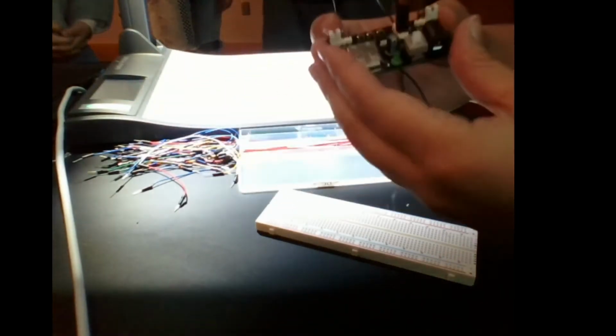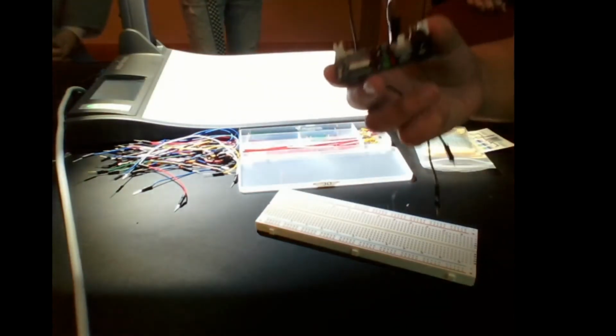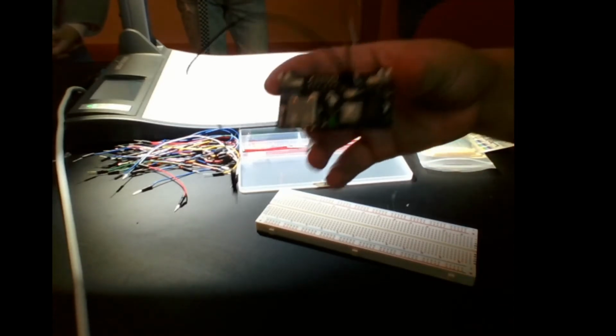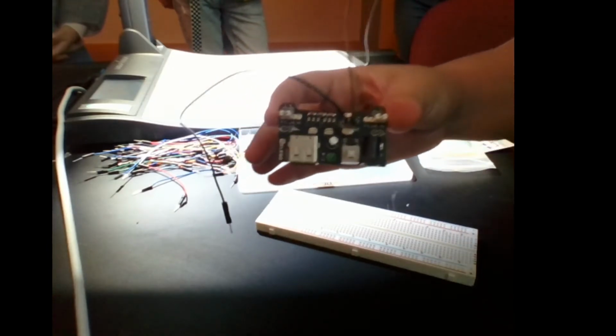Alright, so this is the power supply module that we will be supplying at CuseHacks. Basically you have your plug-in from the wall that'll go into this jack right here. The diagram is also on the slides, so the DC input jack is what I'm referring to. It actually has different kinds of voltage that it outputs. So you can have either 5 volts or 3.3 volts. Usually I like to use 5 volts, it's just more general, but sometimes when you have more sensitive electronics, you'll want to go with a lower voltage so you don't fry anything. So that's just a very simple explanation of it.